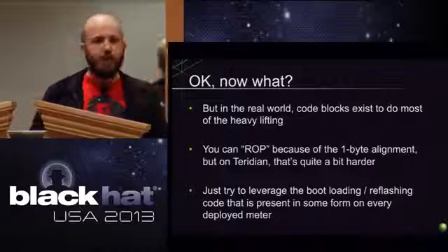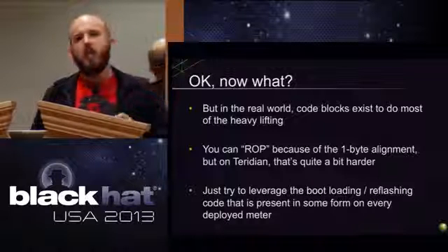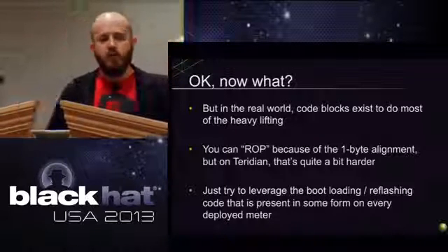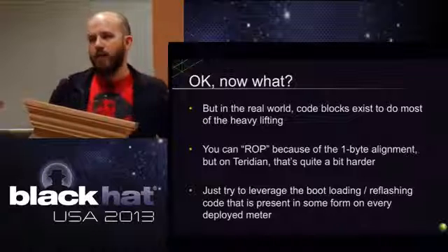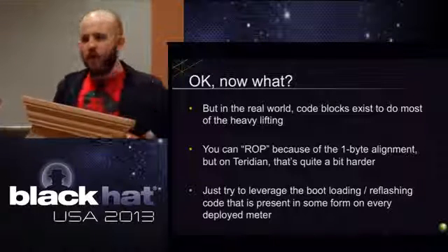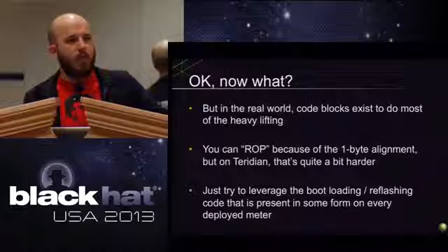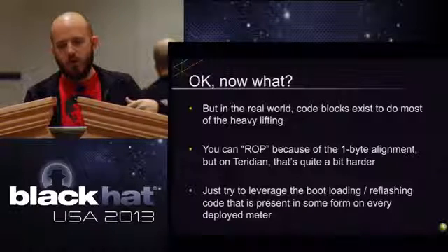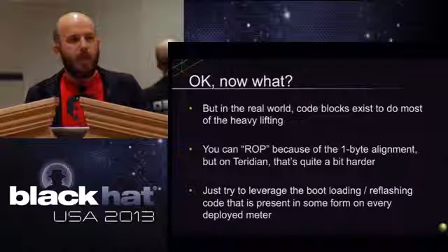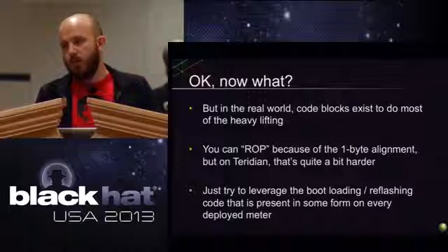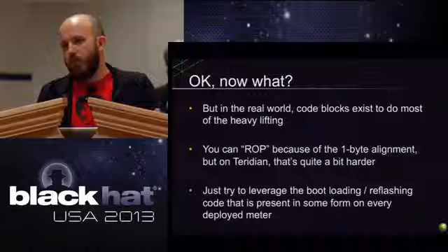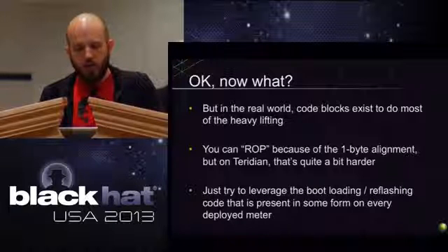It disables interrupts, turns off the CE, flips the bit, and then copies a particular value from over here into flash memory. Then it reverses itself and steps back out. So that code's going to be there somewhere already. For this, we just copied another library from Teridian that gives an example of how to do it, a great public example. We stuff that into our code, and that's what we end up leveraging in the exploit in a minute.